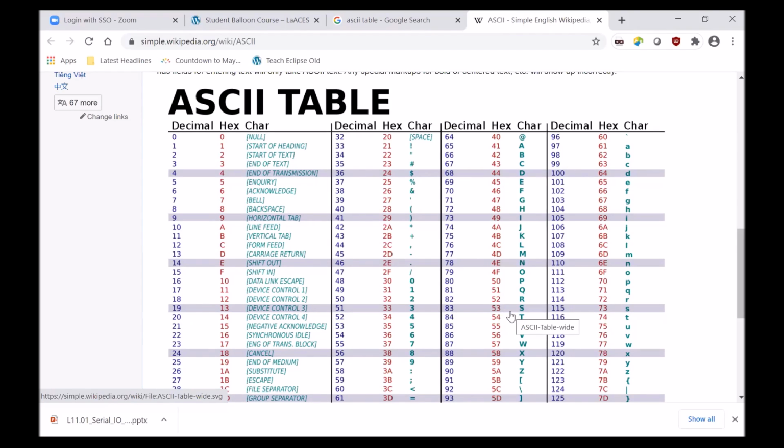Whereas within microcontrollers, sometimes you can denote numbers as decimal or binary or hex. Those are the typical things that I have used. So you just want to make sure you understand what numbering system you're in and what you're displaying information as. The point being, if you send a decimal character to be displayed, denoted as decimal, to your monitor, then it may not get displayed properly. Okay, I'm going to move on to the lecture now, but I just wanted to share that.